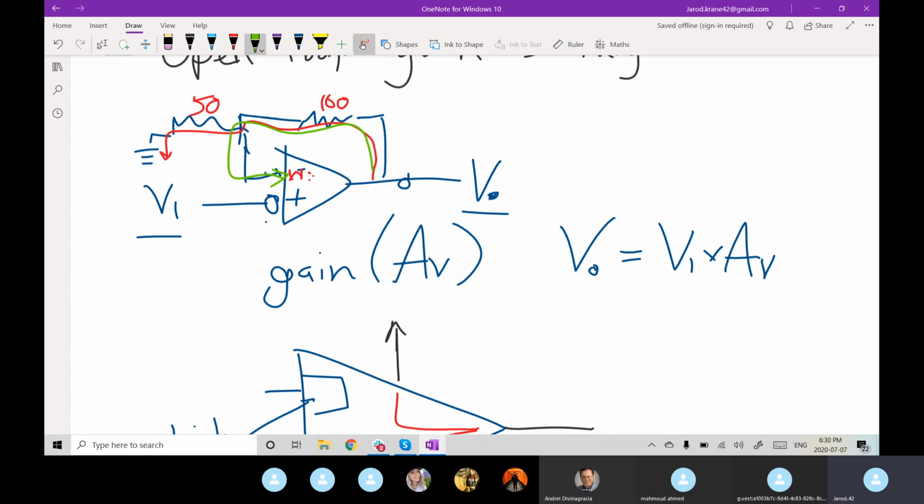So by doing that, you would negate your voltage divider, or the resistance of the voltage divider changes, so the voltage that it produces isn't going to be what you're actually designing it to do.